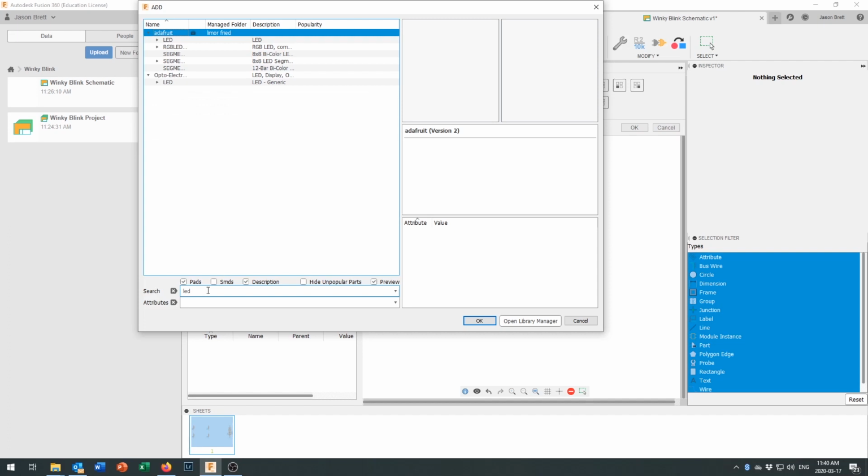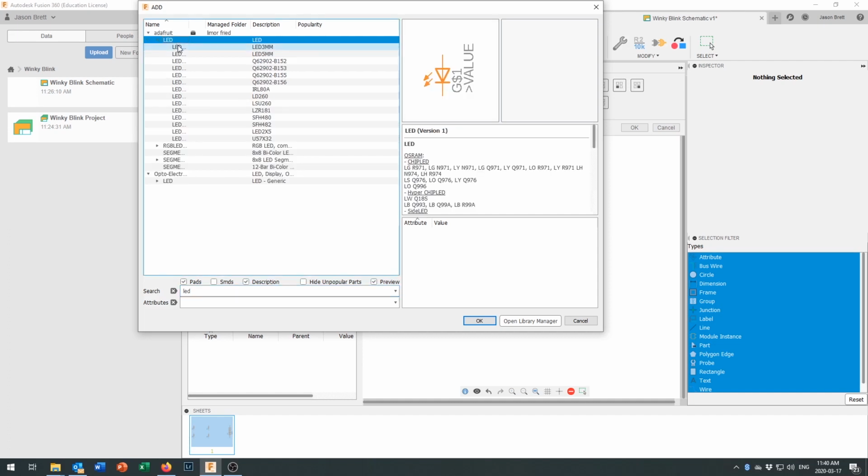And there we go. I just came down here, and to redo that search, I turned off SMDs, clicked on there, and hit enter and redid the search with the surface mount devices turned off. And what do we see on here? Well, we've got some drop downs, and we can click on here, and that looks like a typical LED. We've got the correct symbol right here. That looks like a standard footprint.